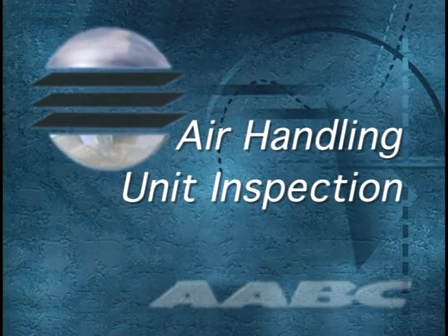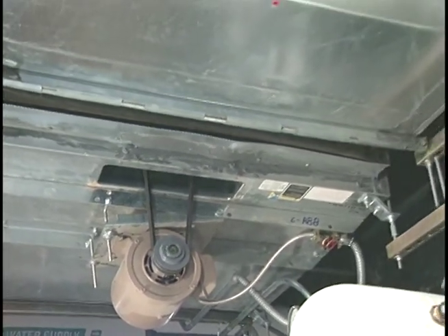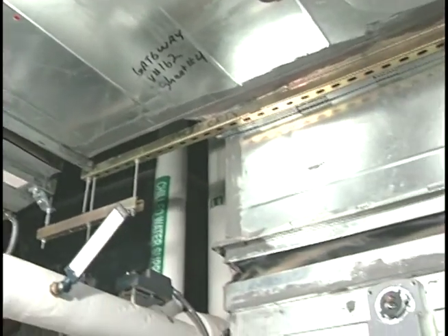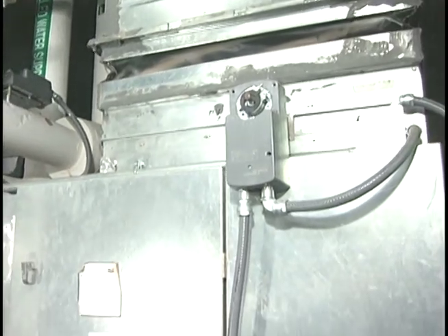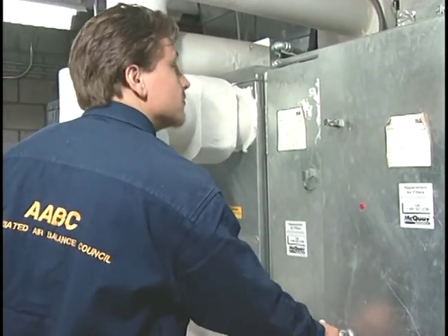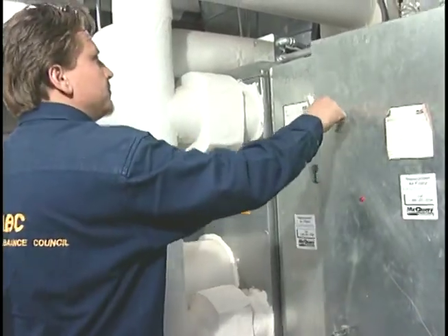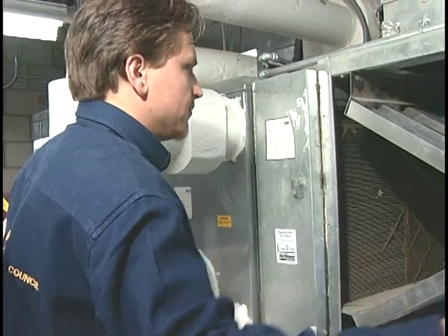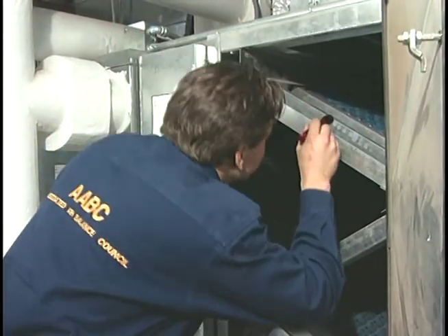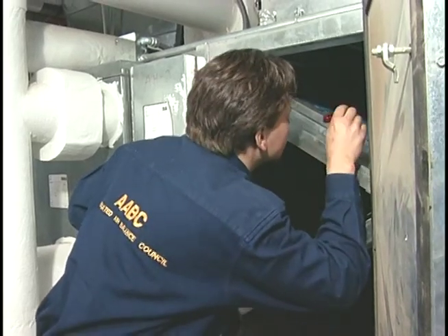Air handling unit inspection. At the air handling unit, the technician checks that the fan housings, plenums, flexible connections, etc. are installed according to the drawings and specifications and are properly sealed. Starting at the mixed air plenum, the technician inspects dampers, filters, and coils to determine if they are clean and properly installed. The drive components are next.